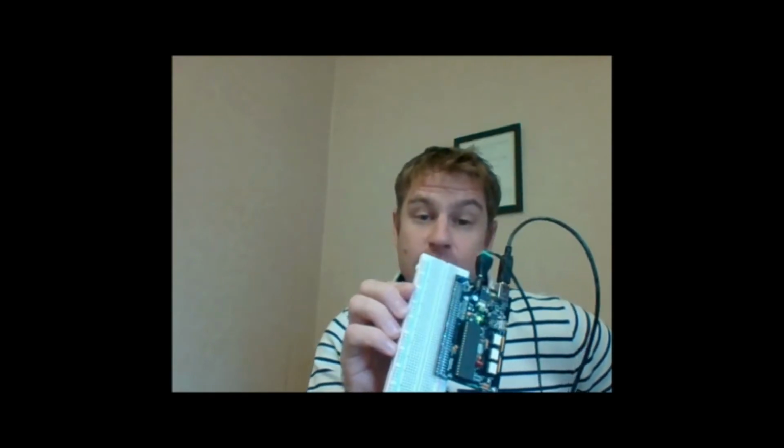Okay, so now what do I have? I have a supply rail, a ground rail, and then I can extend my headers and build some circuits around here. Okay, so I'll do this again. This is my supply rail. This is my ground rail, and this is the header over here that extends so that you can build circuits between these horizontal traces. So it's actually giving you a lot of flexibility. I'll show it to you a little bit later, but this is what it looks like.